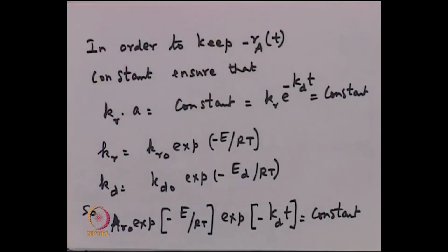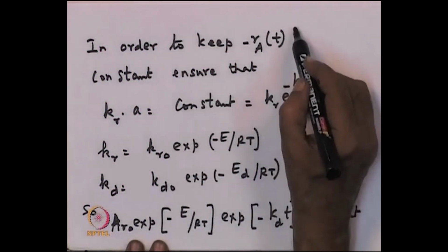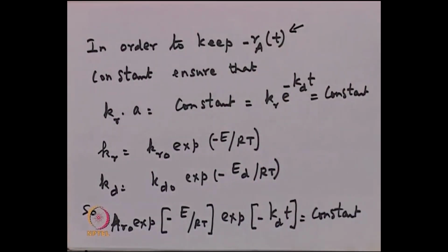What are we saying now? What we are saying now is that our reaction rate RA is changing with time, and this is something that we have to accept, because as the process is running, due to a variety of factors on the catalyst, sintering, maybe coke deposition, maybe poisoning, we do not know, it could be different in different situations, the activity is on the way down.